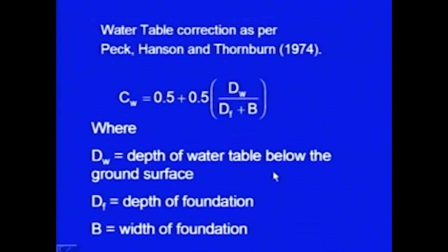So, friends, I have discussed the plate load test in detail. Please remember, this test basically is for cohesionless soil, and we try to simulate the actual behavior of the footing in the field. We take a test plate, that plate is loaded, the settlements are recorded, and the load versus settlement relationship is drawn. From that relationship you can work out the bearing capacity, or if the permissible settlement is available for the foundation, you can work out what should be the allowable pressure. Let me illustrate the method by using an example.